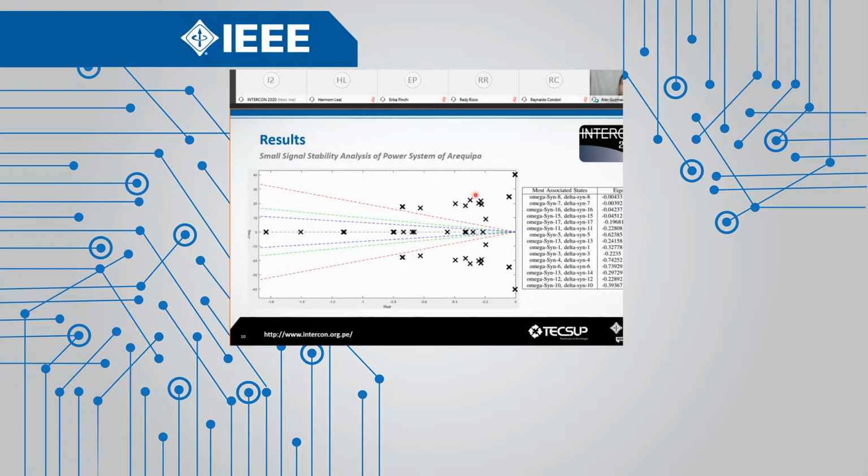In our case, there are 3 particular values, but this picture doesn't show which bus bar it is. Well, an important step is the small signal stability analysis. PSAT provides us the graphic of all eigenvalues. These eigenvalues are given in a report, shown in this table. There is a particular feature of these eigenvalues: all of them have a negative real part.